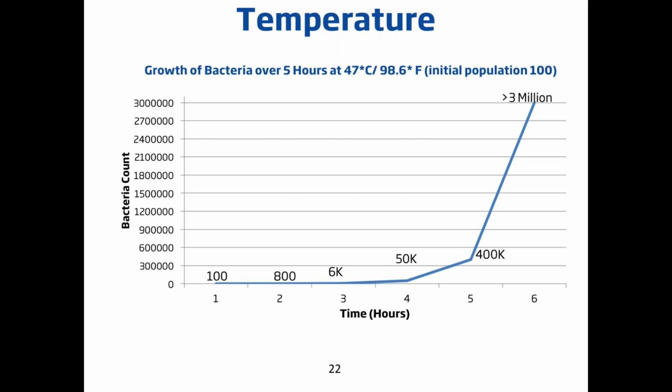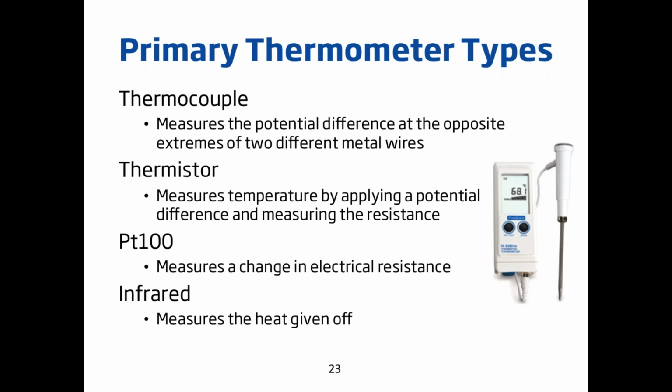So if any of those are harmful bacteria, it's easy to understand why food safety concerns and why outbreaks and illnesses can occur. So there's a couple different types of thermometers that you can use to measure temperature. And what's going to determine which of these technologies is the best fit for your application is what range you need to be in, what accuracy you need, what the response time is that you need, and whether or not there are specific probes that you need as well.